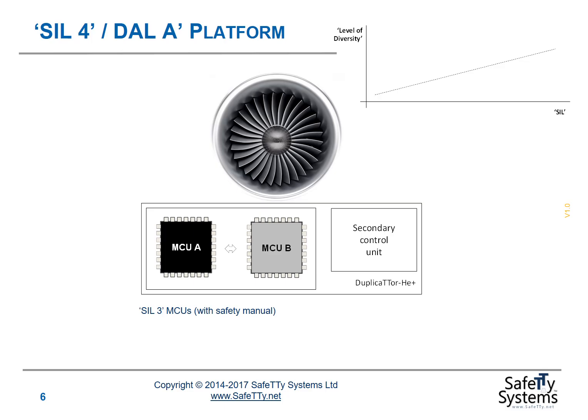Each of these would be SIL 3 microcontrollers with a safety manual, but we would deliberately choose different microcontrollers, probably from different manufacturers, potentially even with a different core, to provide a basis for our application. This is likely to be required by certifying authorities when creating such a design.